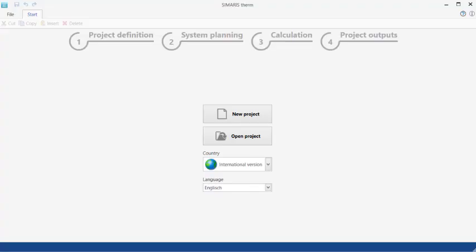Before we jump into a calculation, just to give you a scenario. We've seen both sides of the scale when it comes to customers doing calculations. A lot of customers, if they don't do a calculation, assume which fans or which heat dissipation method they're going to use on their panel. For example, we've seen customers put in a fan on each panel, and when we've actually done the calculation afterwards, we found that one of those fans would have been enough for the heat loss.